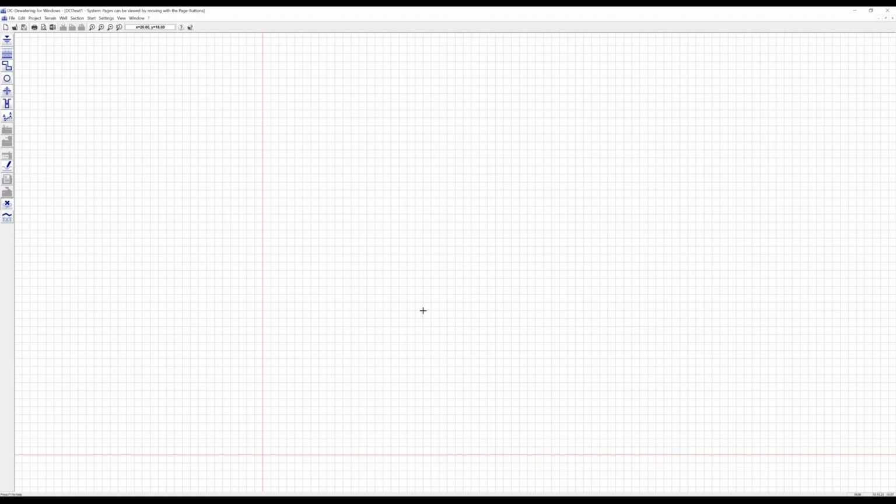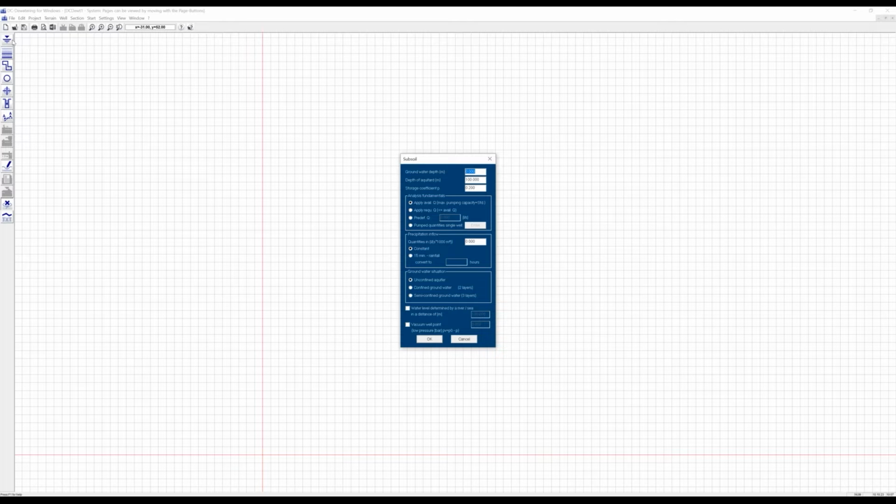So if we have these configuration parameters, we can start with the basic parameters for the analysis. First of all, we have to know where is our groundwater level without dewatering. So the depth is, for example, 1 meter and 50. And in which depth do we have the aquitard, which is the base, the impermeable base soil layer. It might be at a depth of 18 meters, for example. The storage coefficient is used only for a time-dependent reach. We will see this later.